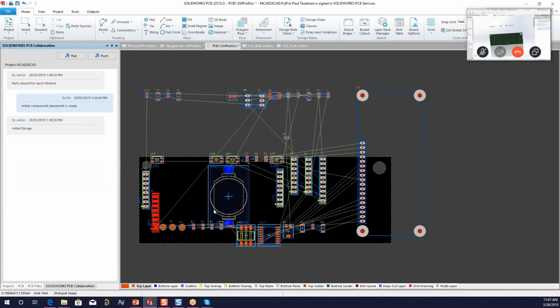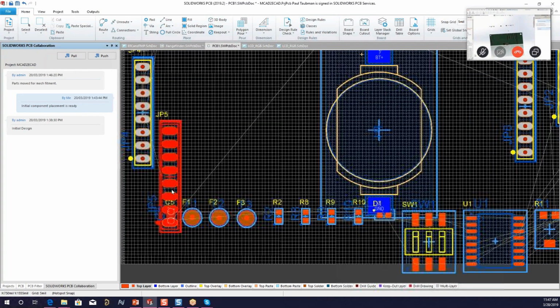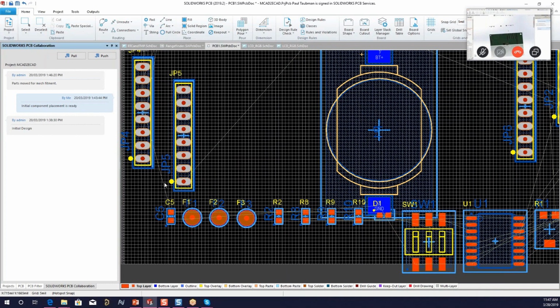It really can push the stuff to and from between the electrical and the mechanical sides of the tools here almost pretty much seamlessly, right? And that's what you were able to see here today. Okay, Paul, you might want to mention too, I'm sorry, mention that on the mechanical side, I don't know anything about clearances in electrical. So depending on how the footprints are, I could potentially move a part that fits in the mechanical world but doesn't fit in the electrical world. And so it's very important to make sure you go back and forth and make sure everything fits. So even though I've moved something on the mechanical side, I can't assume that that's going to work.